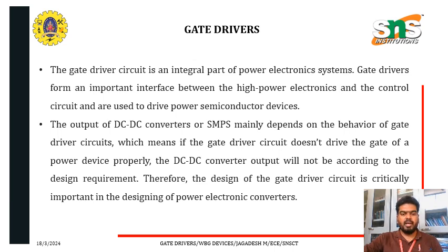Gate drivers form an important interface between the high power electronics and the control circuit, and are used to drive power semiconductor devices. The output of a DC-DC converter or SMPS mainly depends on the behavior of the gate driver circuits, which means if the gate driver circuit does not drive the gate of the power devices properly, the DC-DC power converter output will not be according to the design requirement. Therefore, the design of the gate driver circuit is critically important in the design of power electronic converters.